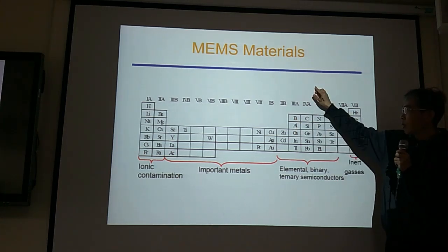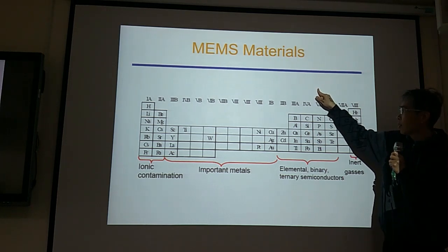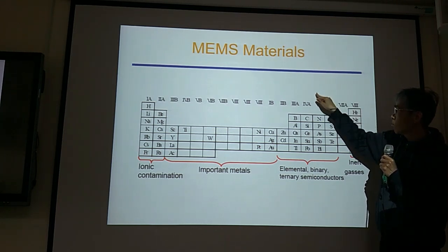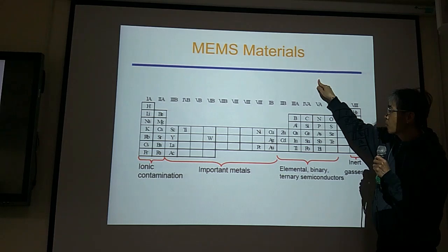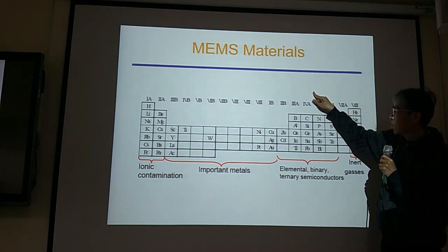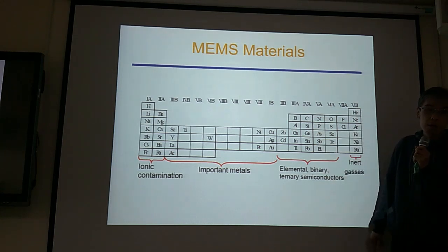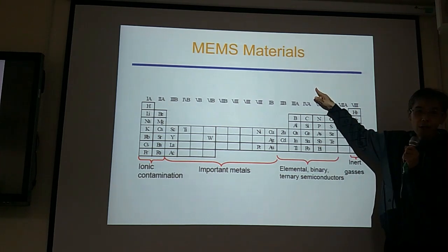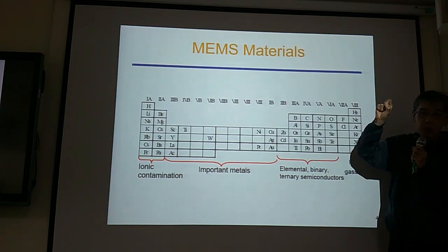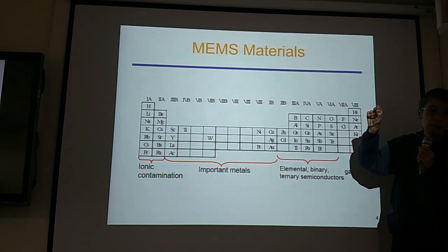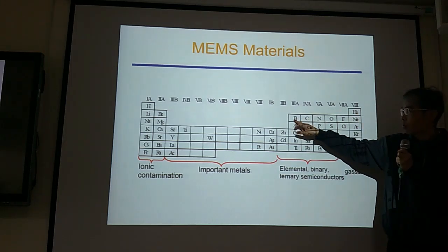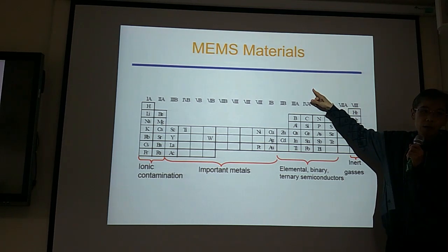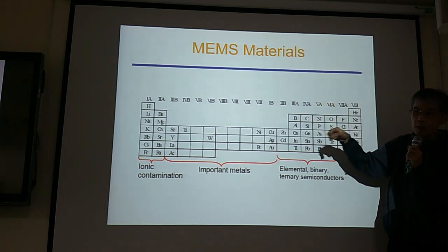So imagine silicon, silicon, silicon, silicon, and 1 boron here. And silicon has 1, 2, 3, 4. But boron has only 1, 2, 3. So for this silicon, we have only 7 electrons on the outermost orbit. So there's one empty site. So this empty site, we can think is a positive charge. So if we put boron into silicon, now it's a conductor, and the charge carrier is a positive charge.